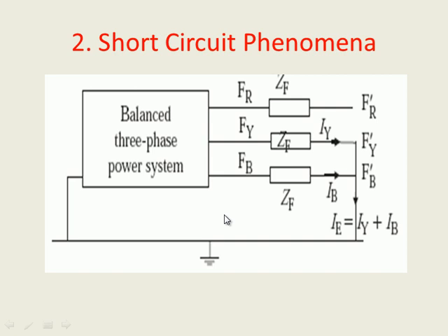Now what happens? The occurrence of a symmetrical fault brings the power transfer across the line to zero immediately. Obviously, if there is a fault, there will be a rise in current and a dip in voltage, as already three lines have been in contact. So immediately the power transfer will be zero, whereas in case of unsymmetrical faults, the impact is only partial.